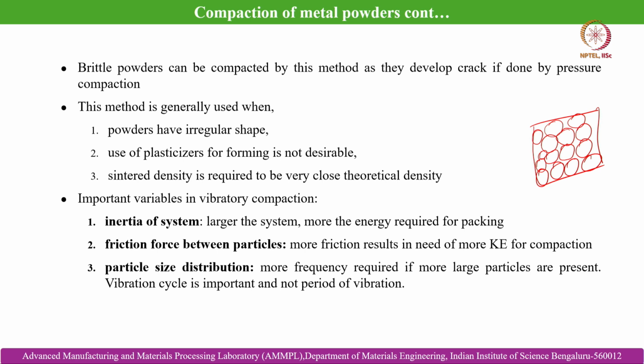Otherwise, there is a chance of crack development if pressure is applied instead of vibration. So, in this case vibration is serving as a replacement for the applied pressure that is generally applied for other uniaxial compaction routes. So, the important variables in vibratory compaction: it is the inertia of the system. This is a powder aggregate which is kept over a vibrating table and is undergoing vibration. The larger the system, the more energy is required for packing.